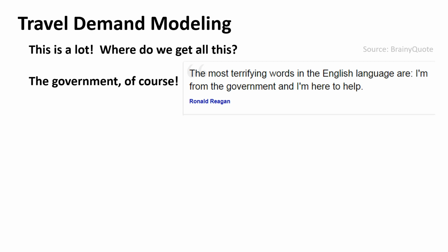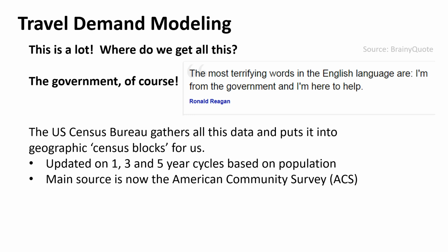Right now, the census is out. You or your parents may have gotten a card saying you've got to fill out the census. I think April 1st was Census Day. For that, you're supposed to fill out the census. That's where we get a lot of this, right? So the U.S. Census Bureau gathers this data, and they drop it into census blocks. They drop it into geographical regions for us, which, not surprisingly, we often use as our transportation analysis zones because we have the data for it. Right. And so that's where we find out the household data.